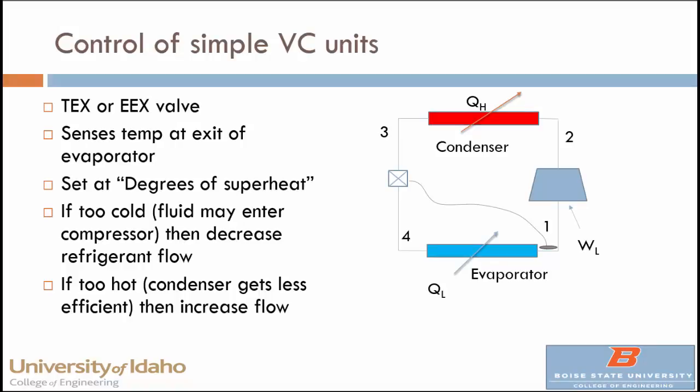Okay, just a little bit more, and then we'll wrap this up. So we assumed that the state at the inlet of the compressor, the suction of the compressor, was pure vapor, saturated vapor. And it needs to be vapor, or the compressor could run into trouble, right? We don't like liquid, which is generally incompressible, in a compressor.